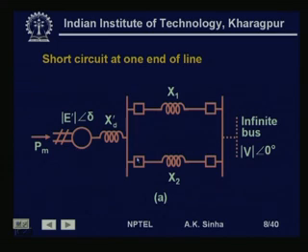Now, if a fault has occurred on this line, let us say, and we have opened the circuit breaker, then we have only one line left in that case. But after some time if we reclose and the fault has been cleared, then both circuits will be on, and so the power angle characteristic will change to the pre-fault condition. However, this recloser has certain disadvantages also.